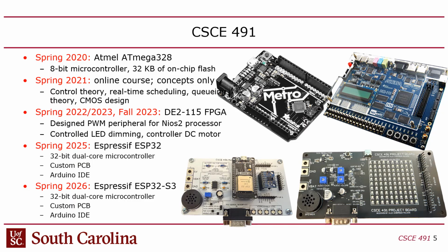Like adults do, right? So we updated to the ESP32-S3, which has a built-in debugger, so you can debug this thing now. And that was a major problem in lab because the code, as I mentioned, is very low-level code where you have to flip individual bits inside these peripherals. And if you get anything wrong, if you're off by 1 bit, nothing works. It just sits and looks at you, right?